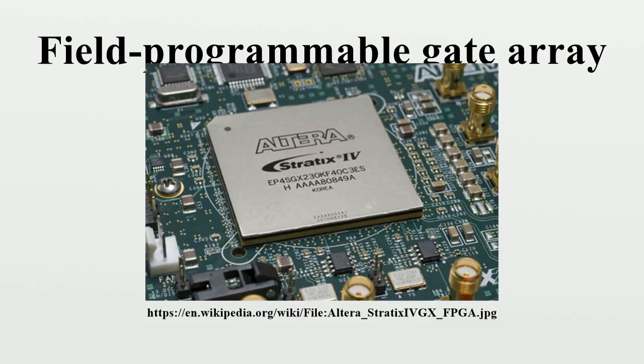An alternate approach to using hard macroprocessors is to make use of soft processor cores that are implemented within the FPGA logic. Nios II, MicroBlaze and Mico32 are examples of popular soft-core processors. As previously mentioned, many modern FPGAs have the ability to be reprogrammed at runtime, and this is leading to the idea of reconfigurable computing or reconfigurable systems, CPUs that reconfigure themselves to suit the task at hand.